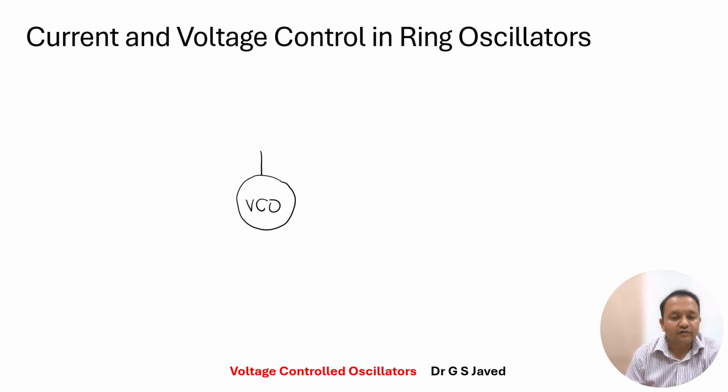So you did find out what is the amount of current that is flowing through. It will have its own switching network to turn on and turn off the amount of currents that you need. In this particular case, as an example, I am going to use 5 current sources. Each of the current sources is going to be binary weighted or thermometric weighted current source.